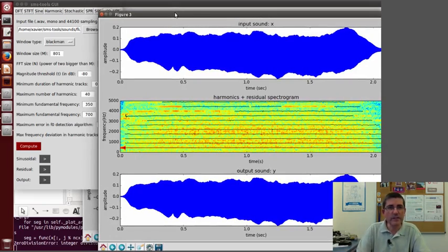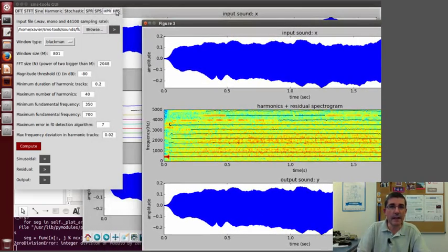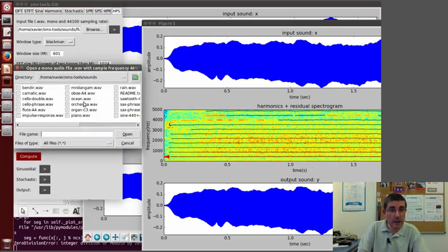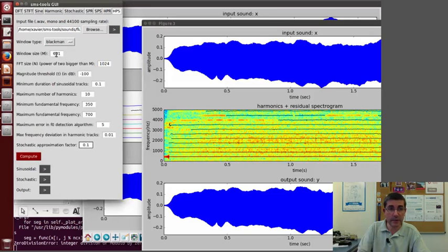So this is very much a stochastic signal. It's very noisy, so that means that we can apply the stochastic analysis to that. So now let's use the harmonic plus stochastic model, and let's get the same type of parameters. Of course, we can play around with these parameters to get better values, but the ones we chose looked okay. So let's put 0.2 here. Let's get the number of harmonics, I think 40 harmonics, and this was all right. This was 7, and this was 0.02.